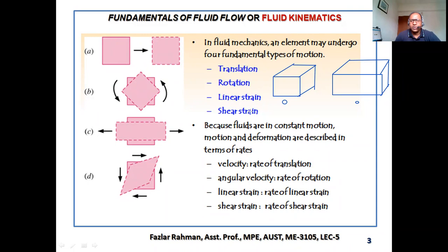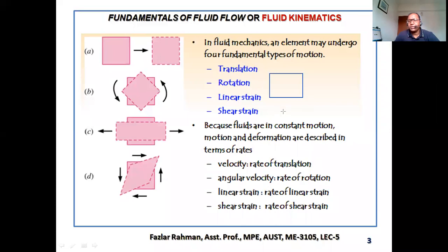Okay. The other one, shear strain. What is shear strain? That means the fluid particle remains right over here at point A. After a few moments, the same fluid particle came in at point B. When it came to point B, its shape changed.